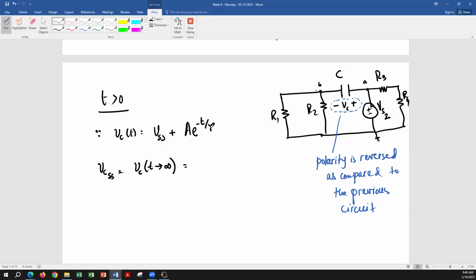Well, we are trying to figure out VC. If you remove capacitor, capacitor is fully charged. It's open circuit. If you remove capacitor, assume you're not removing physically, but you remove capacitor. How much current is flowing in R2 in that case? Zero, exactly. He said it already.